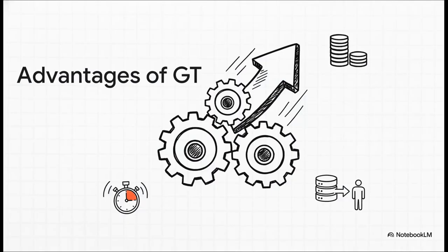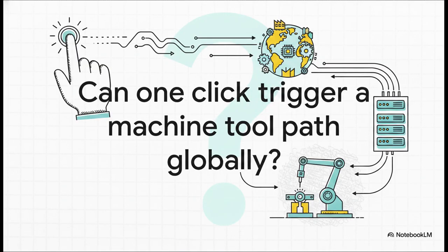And when you link the whole system together, CAD for design, CAM for execution, and group technology for the physical layout, the advantages are just off the charts. You wipe out design duplication. A brand new junior engineer can instantly leverage a master process plan from the database. Setup times completely plummet because the machines are already configured for that specific part family. Manufacturers are seeing mind-blowing savings, ranging anywhere from 5% to 75% across different phases. It's gotten to the point where custom, small batch production can actually rival the sheer efficiency of massive, traditional assembly lines. Which really brings us to the bleeding edge of where all this is heading.